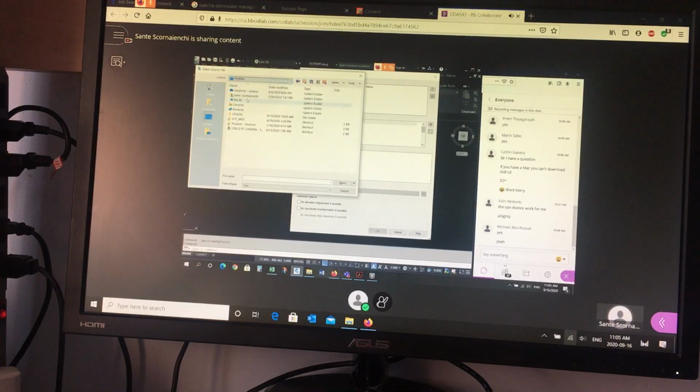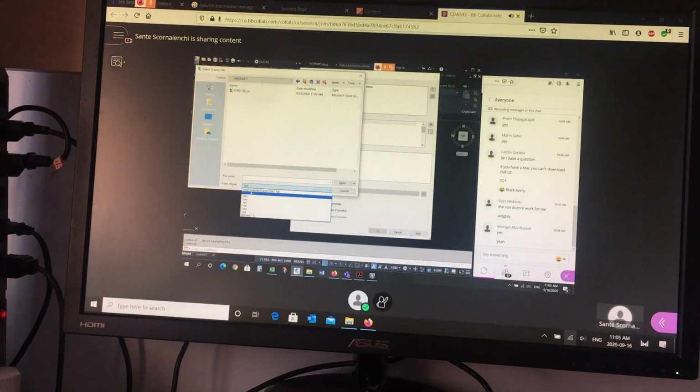So again, go to your desktop, Civil 3D 543, go to your downloads, go to module 1, and if you don't see the CSV files, it's because the file type might be set to XYZ or PNT. There are many different file types. These are all just text files. The type I gave you is a CSV, comma separated value.